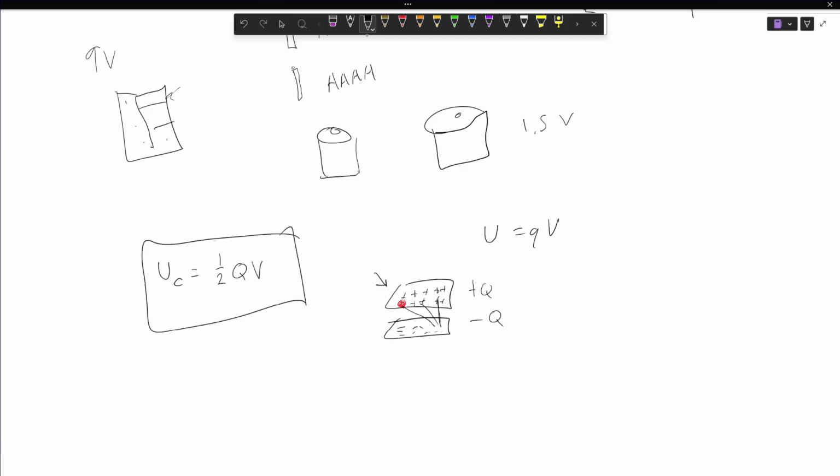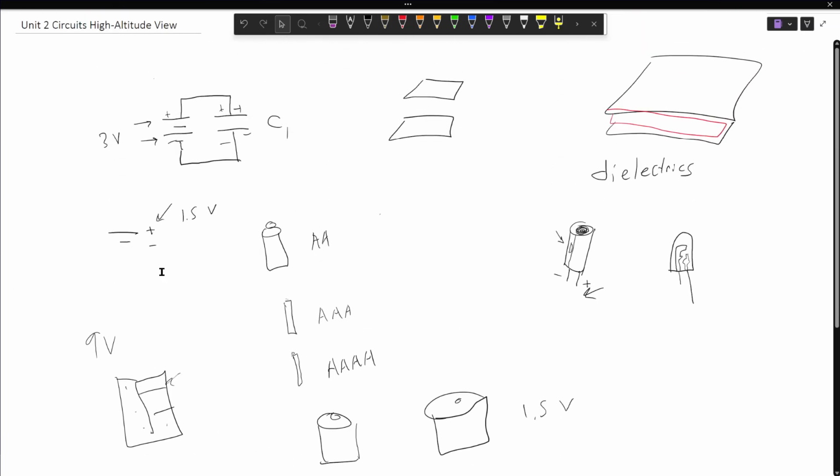therefore guaranteeing this voltage drop, voltage difference, potential drop, all of those words we start using when we're talking about circuit components. And for instance, if I color up here, this entire wire up here is going to be all at one particular voltage. And then down here, this wire is going to be all at one particular voltage as well. And so anywhere you go from red to blue, that's high to low, you have that same voltage drop.